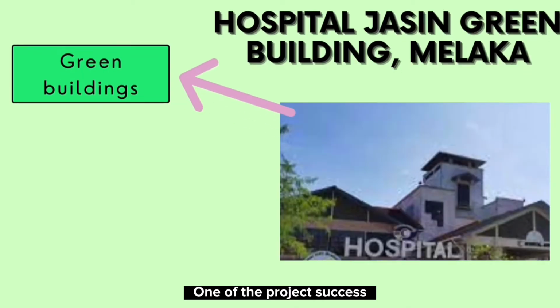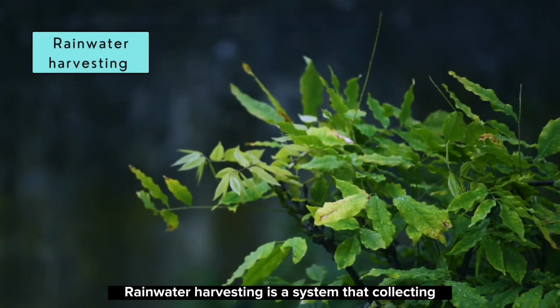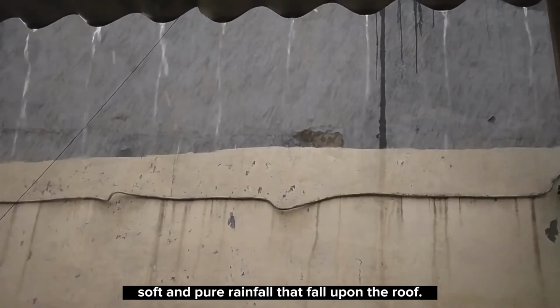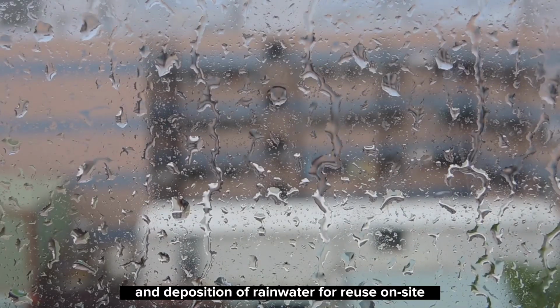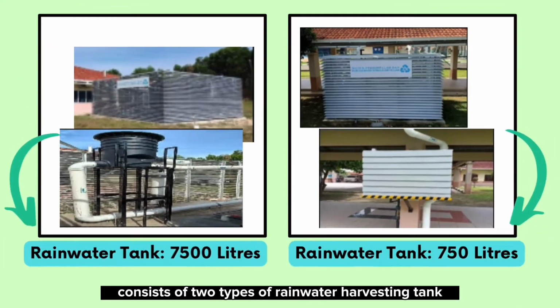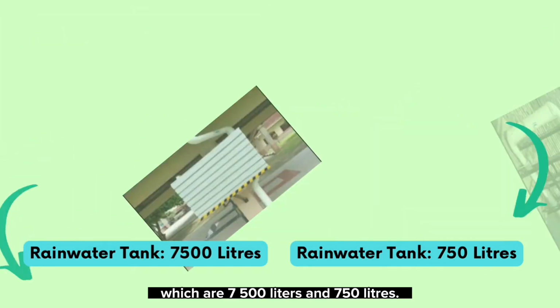One of the project's successes for the green building of the Hospital Jasin is the rainwater harvesting system. Rainwater harvesting is a system that collects, stores, and purifies the natural soft and pure rainfall that falls upon the roof. It is the accumulation and deposition of rainwater for reuse on site rather than allowing it to run off. Sustainable life cycle design applied in this hospital consists of two types of rainwater harvesting tank, which are 7,500 liters and 750 liters.